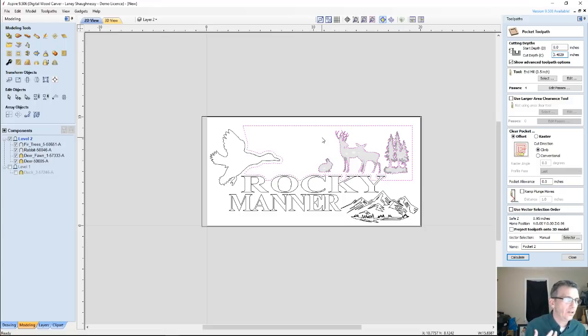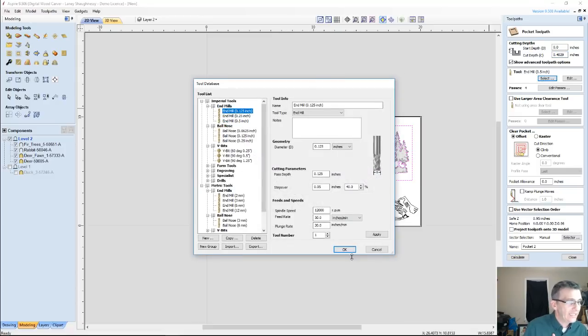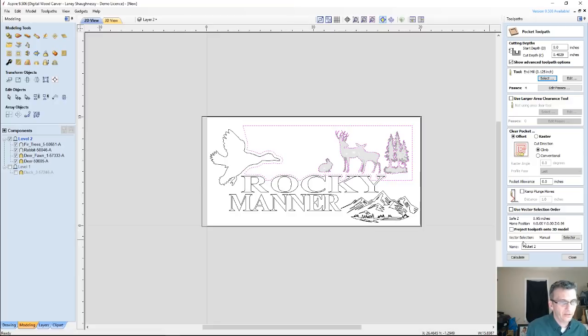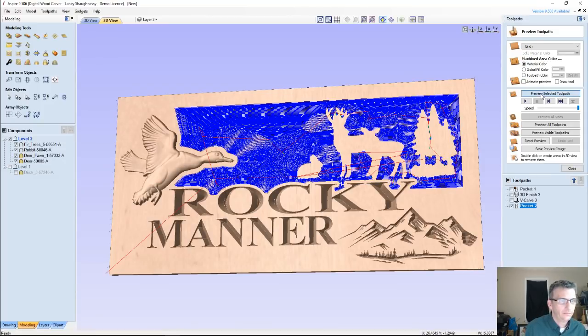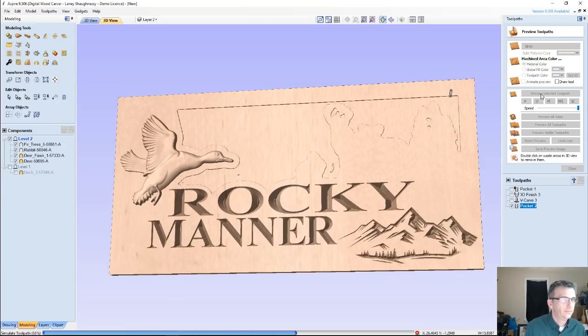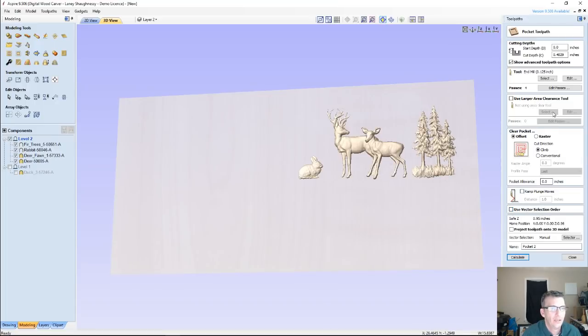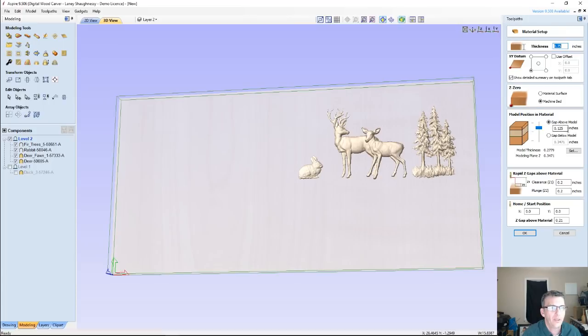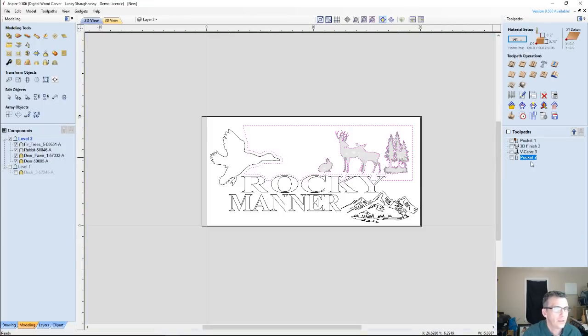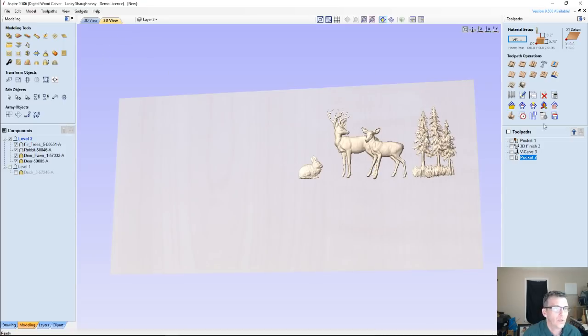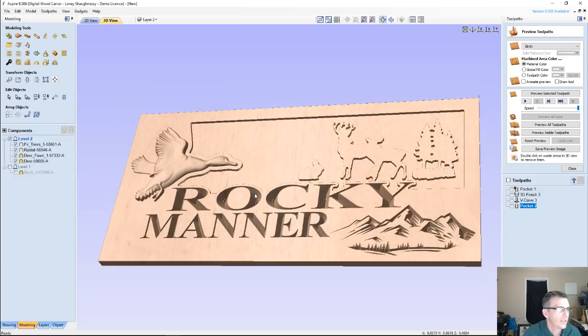All right, because our zero's been milled away and all. So let's find out. I've got to change back to my 1/8 inch end mill. Let's find out if I've milled too much material away. Let's calculate. Oh, actually, I'm an idiot. I actually have to do a little bit of additional math. No, I don't. I put that additional depth in there. So that is my number. Okay, so that's my pocket cut. There's my pocket cut. So I got a little bit of a recess going on there.